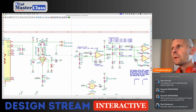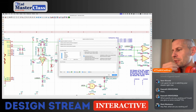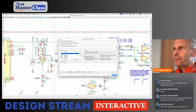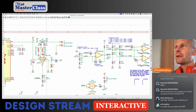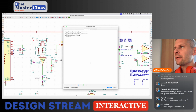When you update the symbols to reflect the attribute changes, etc., it's important to uncheck the value attribute, because otherwise all test points will be reset. So it's not needed. So now I undid the update and redid it without the value ticked.